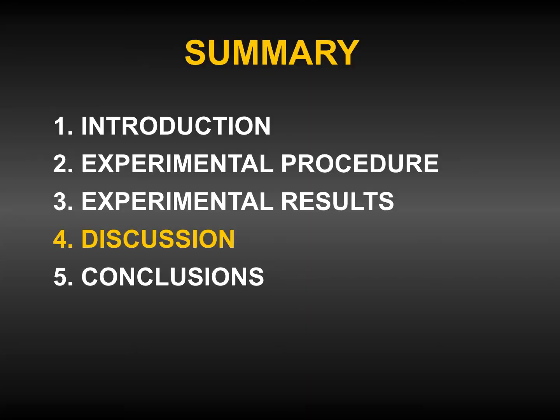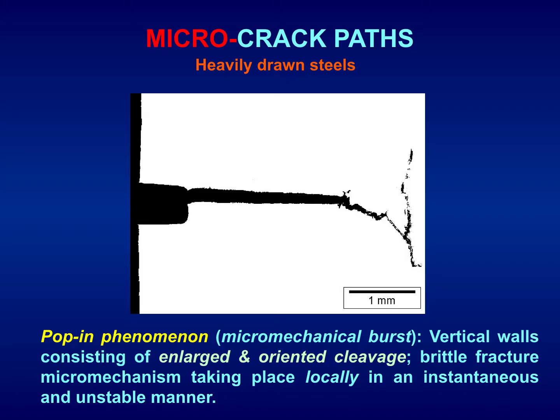Let's go to the discussion. Here we observe the microcrack paths for heavily drawn steels. We observe a certain propagation in mode 2 and mixed mode, anisotropic fracture behavior, crack deflection, crack deviation, and even axial cracking separated from the initial crack tip.